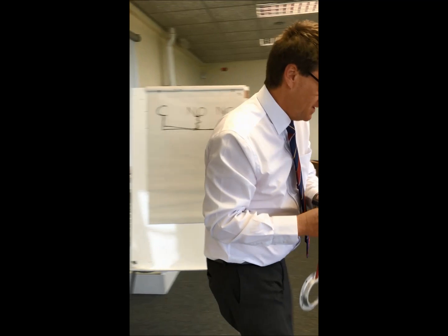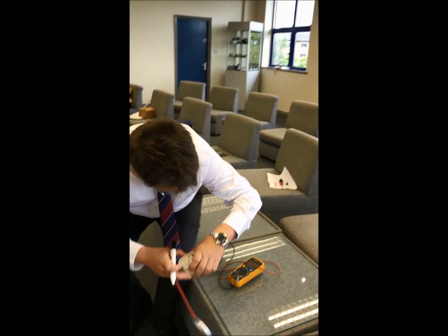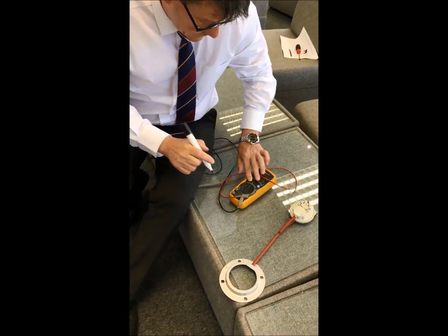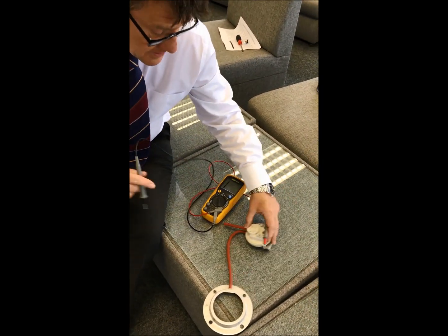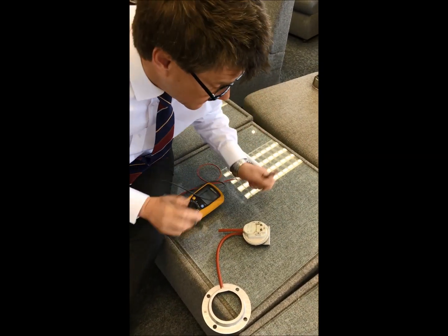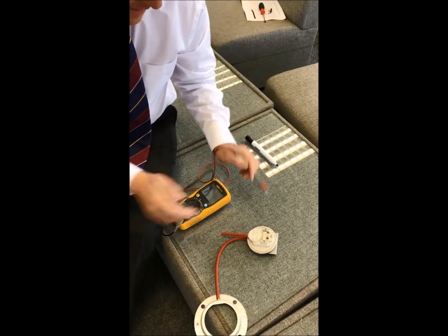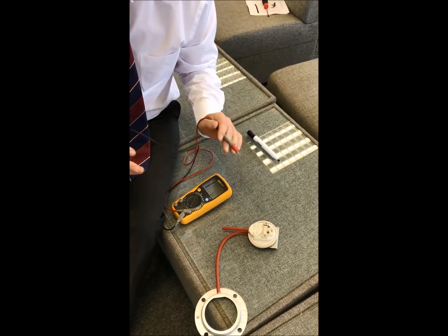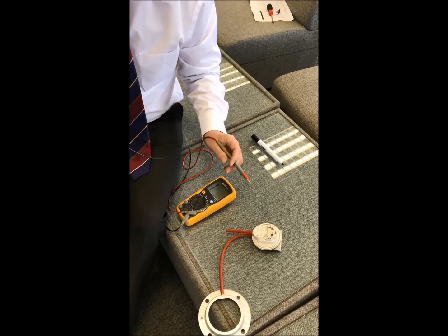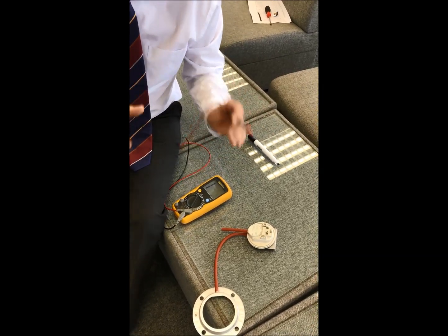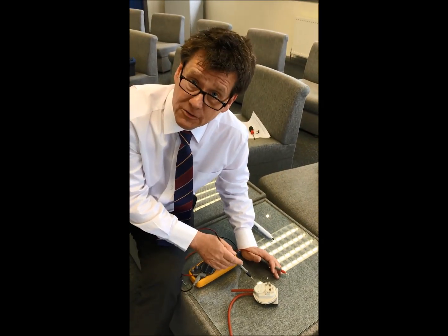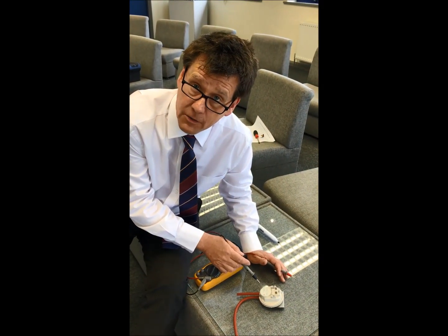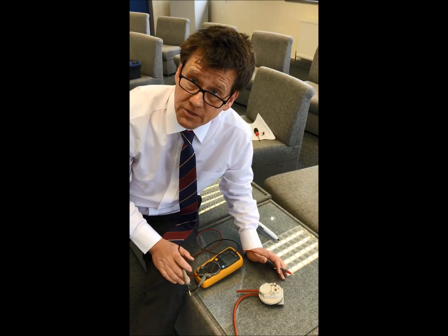Let's just have a look at this. So if I get my multimeter onto continuity buzzer, and I look via the MI, on the air pressure switch it tells me which is common, which is normally open and which is normally closed. Before you attempt to fit an air pressure switch, just remember, guys, that these air pressure switches can have done 20,000 miles bouncing around at the back of you in a van. Is it going to work when you want it to work?